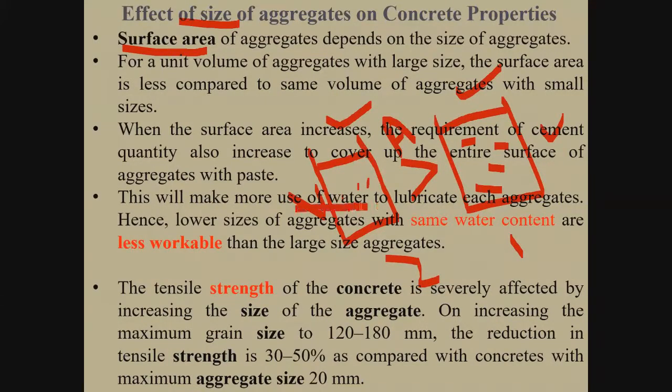Also, more water will be required to lubricate each aggregate. Let's suppose that, due to a pre-set concrete mix design, we cannot increase the amount of water content that will be used in the mix. Then the resultant concrete will be partially saturated. If the aggregates are not properly saturated, then the resultant concrete will be less workable than